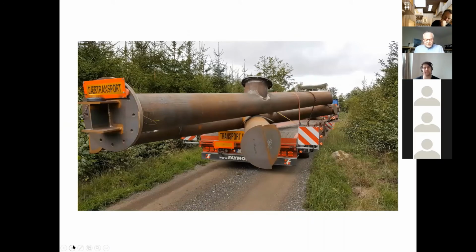Well, the main structure, meaning the parabolic structure with a height of 45 meters, was divided into 4 times 18 elements, in total 72 fabrication elements. 18 elements for the level from 0 to 15, 18 elements from level 15 to 30, 18 elements from 30 to 45, and 18 top ring elements.